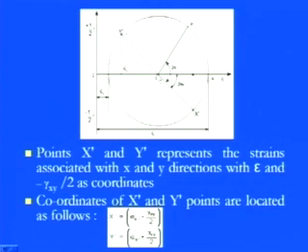So we have the center position, epsilon 1 and epsilon 2 are there. Pretty simple, you can calculate these points, and you also know the radius. Radius was nothing but equal to epsilon 1 plus epsilon 2 by 2. Once you know this, you can get the coordinates of x dash and y dash. You need to plot those coordinates, make the straight diagonal, and draw the circle. If you drop those points, then you will get epsilon y and epsilon x at those particular coordinates.